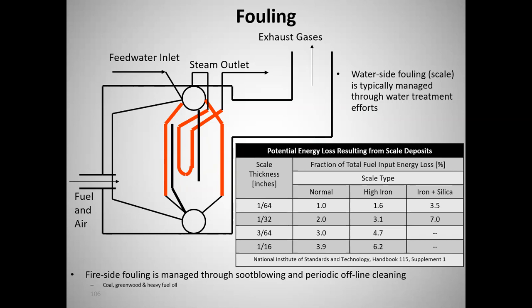It goes down. So the boiler guy, the maintenance guy, he would much rather you soot it up than scale it up, because at least you're not going to wreck the boiler tubes. I mean, he's going to have to go in at some point and clean the soot off, but that's a whole lot preferable to having to acid clean and potentially replace damaged tubes. So big difference between fireside fouling and waterside.